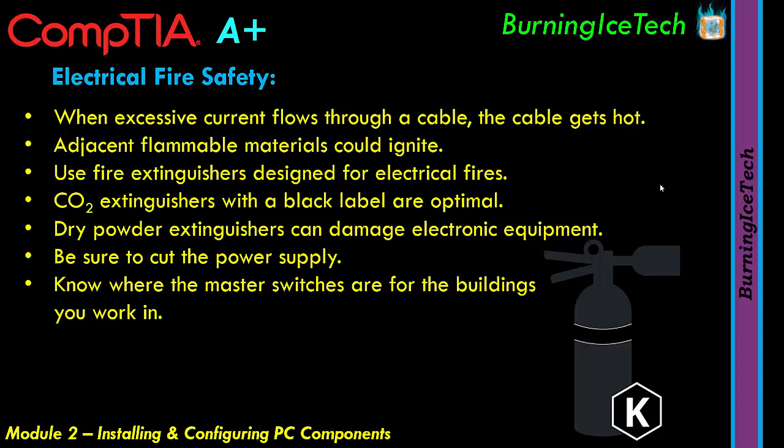Dry powder extinguishers can damage electrical equipment, so just be careful when you use them. Try not to get too much of the powder on the electrical equipment unless it can't be helped. If the fire is coming out of the electrical equipment, then, well, there's no choice about it. Be sure to cut the power supply. That's assuming it's possible. So if it's possible, try and cut the power supply.